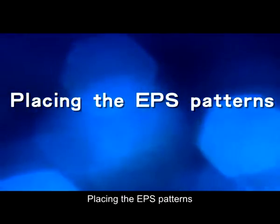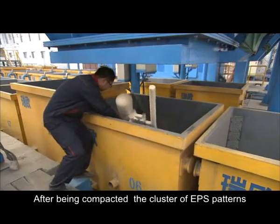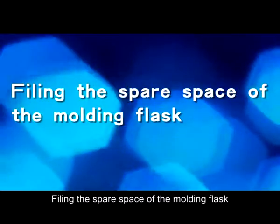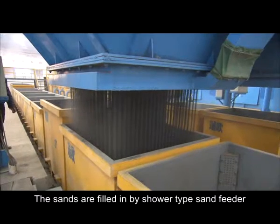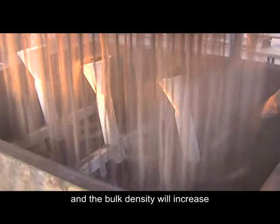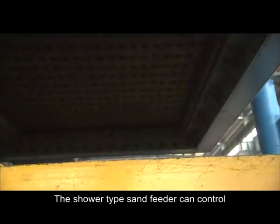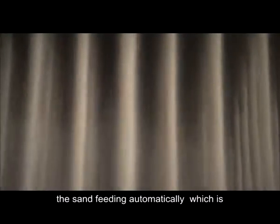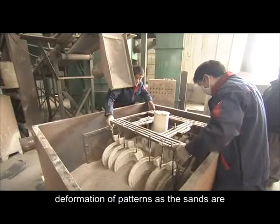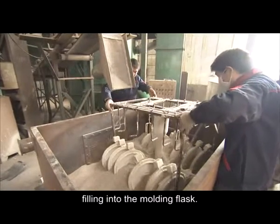Placing the EPS patterns. After being compacted, the cluster of EPS patterns is placed and fixed by adding sand, filling the spare space of the molding flask. The sands are filled in by shower type sand feeder. The sands occupy all the space of patterns by the three-dimensional vibration, and the bulk density will increase. The shower type sand feeder can control the sand feeding automatically, which is featured with uniform and quick sand feeding and light shock to the patterns, avoiding the deformation of the patterns as the sands are filling into the molding flask.